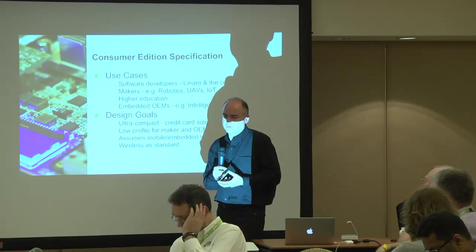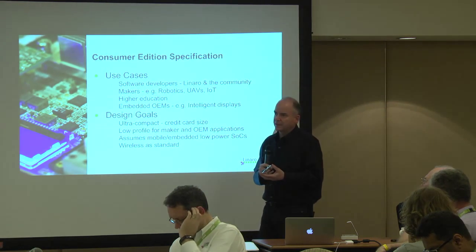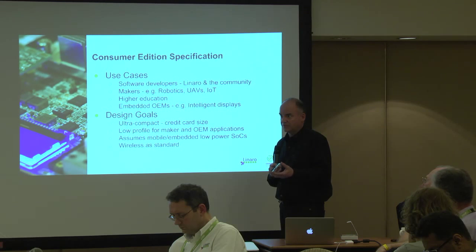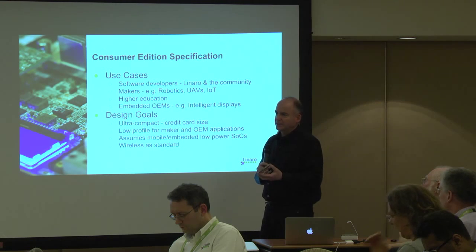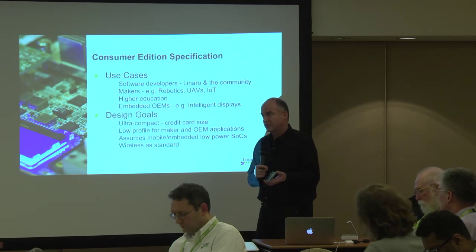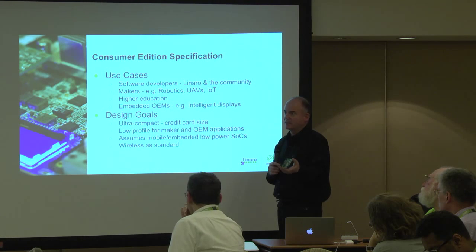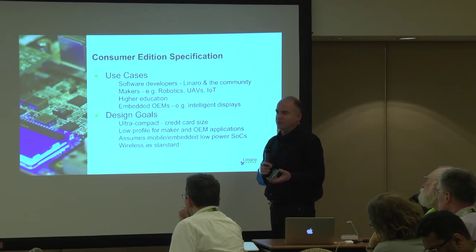This is a minimum specification, right? Vendors are free to differentiate in any way they want as long as they don't go below the minimum spec. The problem is that in an initial implementation, if you're using an SoC, for example, that doesn't have an HDMI interface, as this one was, you have to have a bridge between DSI and HDMI. You may need a USB hub.